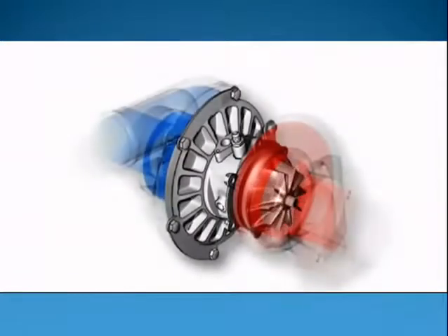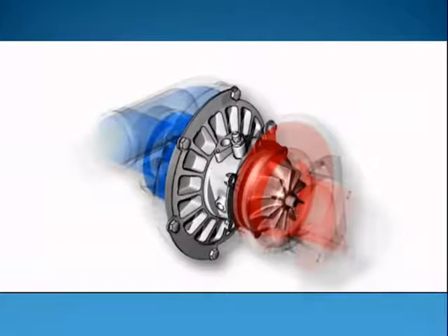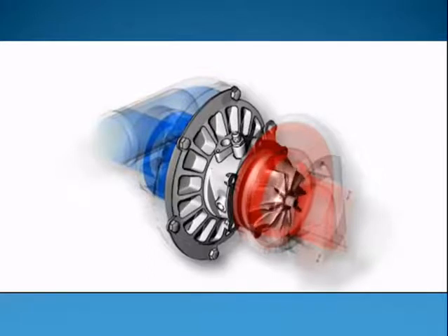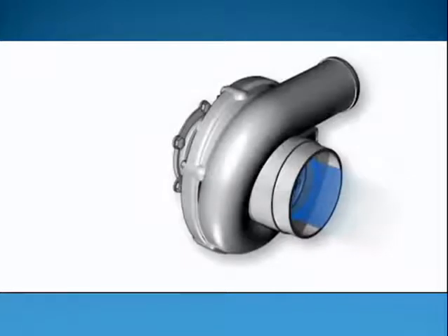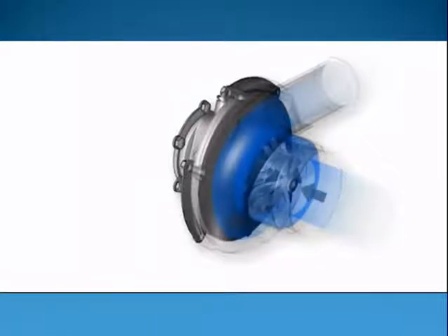Mechanical construction of an exhaust gas turbocharger. The compressors of most exhaust gas turbochargers are radial flow compressors, otherwise known as centrifugal compressors. This type of compressor consists of three main elements: the compressor impeller, the diffuser, and the volute casing. Fast rotation of the impeller axially inducts the fresh air which is to be supplied to the engine compressed and accelerates this air in the impeller to high speeds.